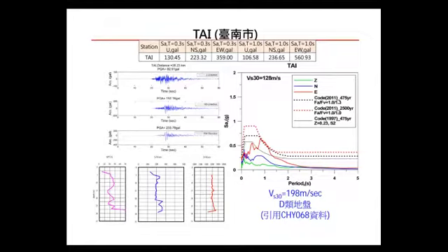This probably doesn't have much to do with the structural response, but it will have a lot to do with the liquefaction potentials because you have a lot of stress reversals during this duration. The other thing I want to point out is that at 1 second period, the structural response has a peak, again in the east-west red direction, much higher than the blue direction, the north-south. You can also see on the time history, there is a very strong long period duration that is representing this peak right here. Does this peak in the structural response at closer to 0.8 to 1 seconds have anything to do with the collapsed building? It will be discussed more in detail later.